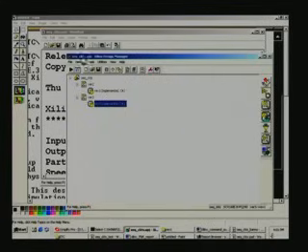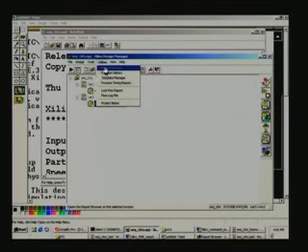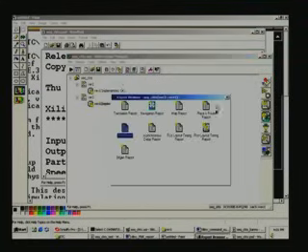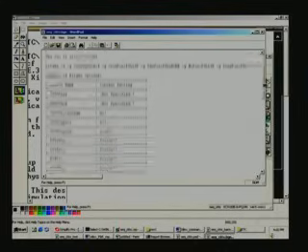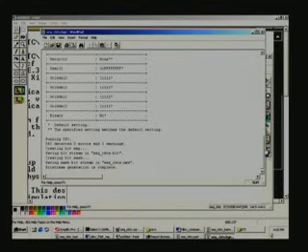So coming back to this design manager here, so as I mentioned, you can use this utilities, then click on report browser, then you can open one file after another and find out what they are. If you are interested in say bitgen here, let me have a look whether it gives any new information.